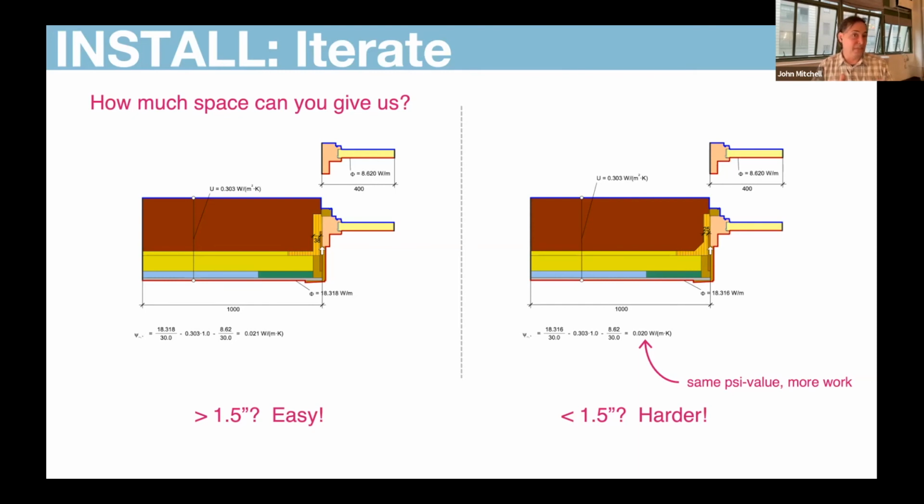But we need a significant amount of insulation there in order to not have a really bad thermal bridge there. And the question is always how much? And really the question is how little? Because nobody wants to give up any space, and we want our windows to be as big as possible. We don't want to have the windows shrunk in the opening or things like that.